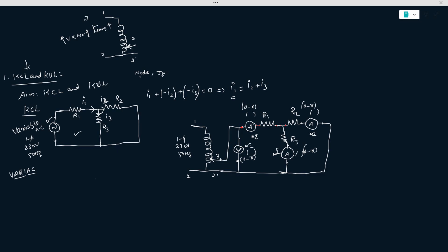So, general mistakes made by the students: the voltmeter is always put in series with the elements. That is a blunder. So to avoid that, we need to place the voltmeter last, after all connections are over.